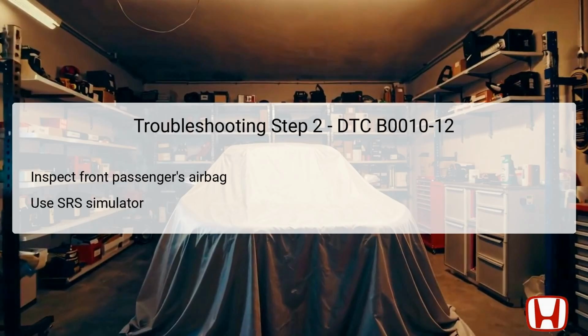warranted. In the third step of troubleshooting DTC B0010-12, you'll need to examine the external circuit, particularly the wires leading to and from the SRS unit. Begin by disconnecting the SRS unit connector A and the front passenger's airbag inflator connector to isolate the circuits for testing. You will check for shorts in the power supply pathways RA1+ and RA1-.